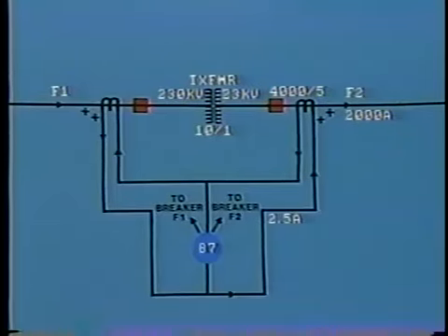For this condition, the high voltage primary current will be 200 amps, ignoring transformer losses. And in this case, the chosen CT ratio will be 400 to 5 to give equal secondary current, 2.5 amps. However, in practice, there are transformer losses and also losses associated with the CT secondary leads, which may differ considerably in length due to station layout.